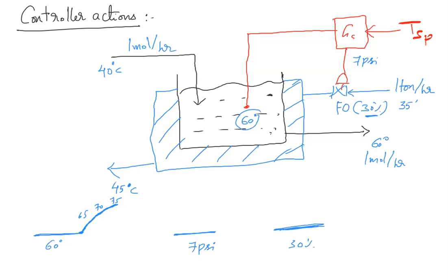If you see suddenly 65 in the CSTR, should you increase the cooling water flow rate or decrease? You need to push more cooling water. Now to increase the percentage of opening, what should the pressure signal be? Does the pressure signal decrease or increase? Decreases because it is air to close type.